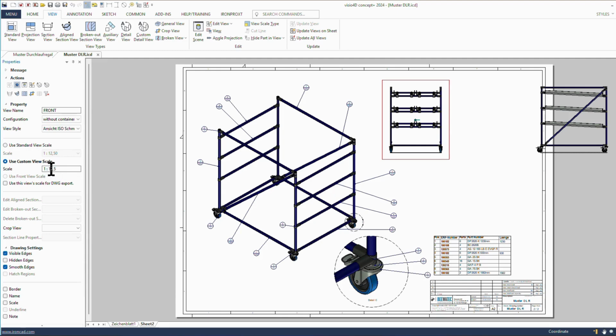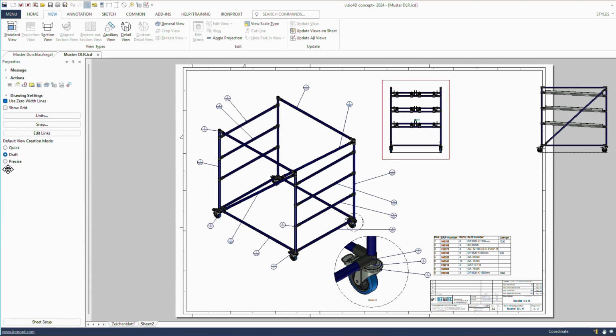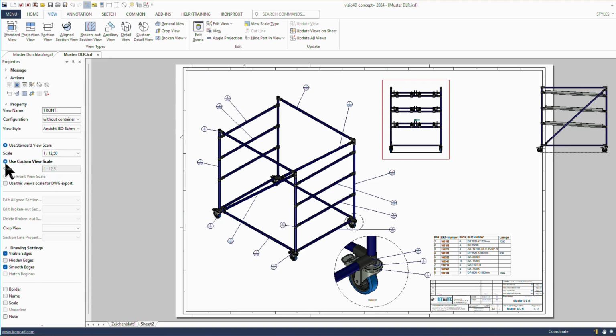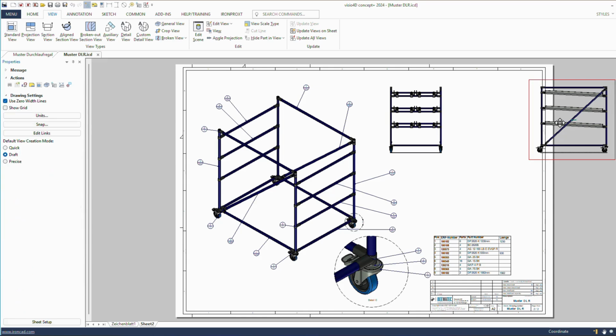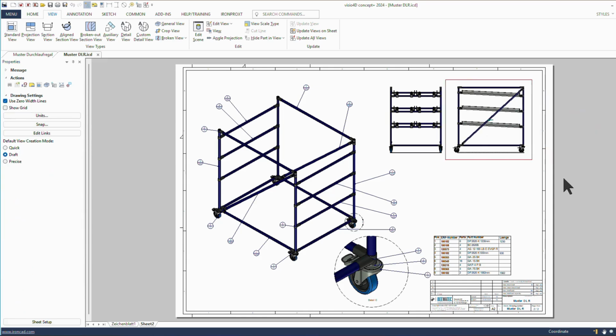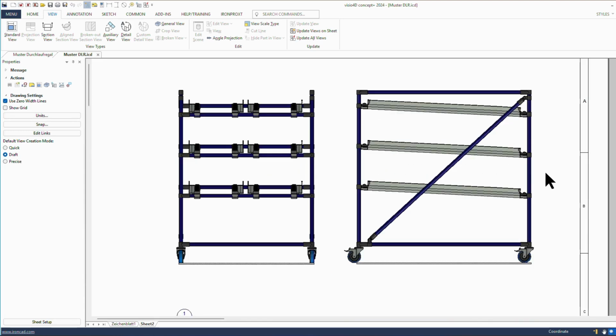In the construction drawing, we have a slightly different structure to that used for functional dimensioning, as shown on the first page. In this drawing, we ensure that we always have clear dimensions from joints to joints. For the fitter, this isn't necessarily all that important, and at the start they don't have a floor reference point where I can say, from the floor up to this height, we have an exact measurement. Instead, they only ever have clamp to clamp measurements. That's why we always have measurements from joints to joints or from clamp to clamp.